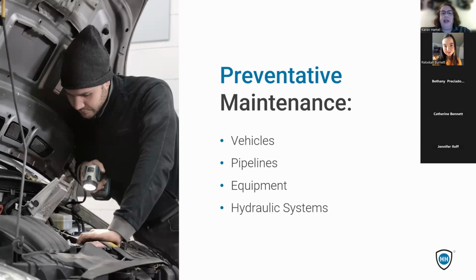Likewise, I've got a gas furnace in my home with forced air. And when the technician installed the furnace, he told us that if we change out the filter every month, we will get 7 to 10 more years out of our furnace than if we don't do that. So every month, I've got it set up. $1.59 for a filter. It takes me about 3 minutes.